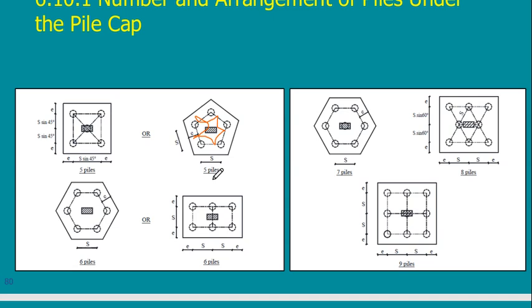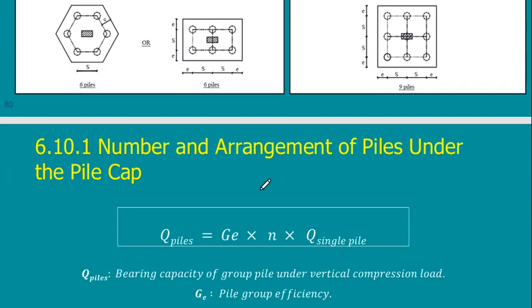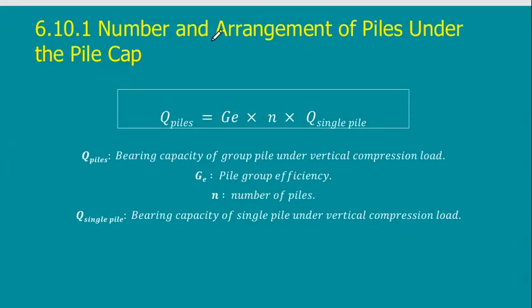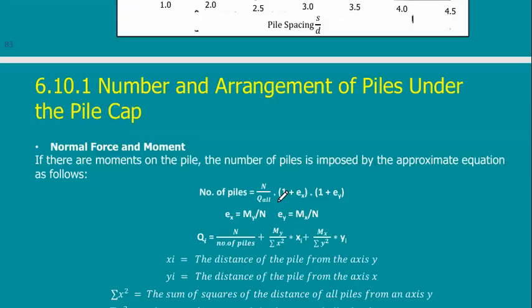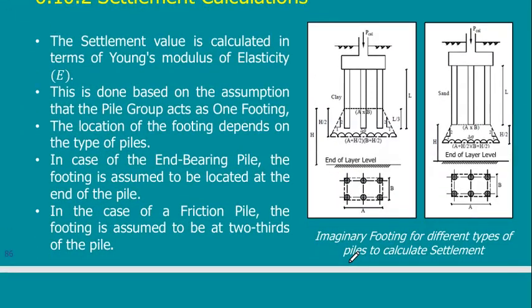ton, maybe it is 900, 800, 700, depending on what we call the efficiency of the group, how piles are crowded together or away from each other. So this is also important, what is the geotechnical capacity of the group, or the group efficiency of my piles. I think the last thing is the calculation of settlement. Now I know the load of the pile, I know the load of the group. Are they going to work together and settle, or do they stay in place?